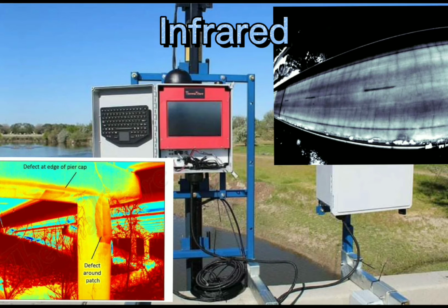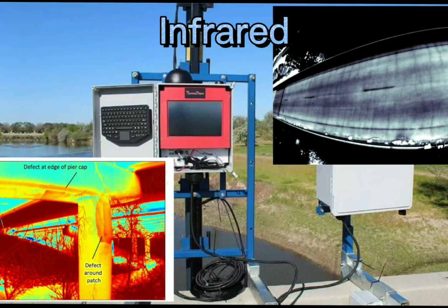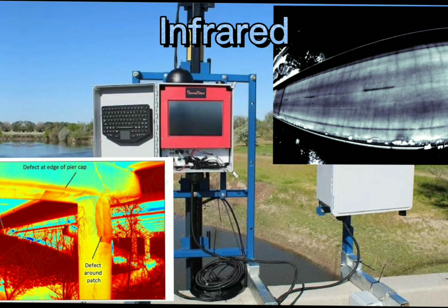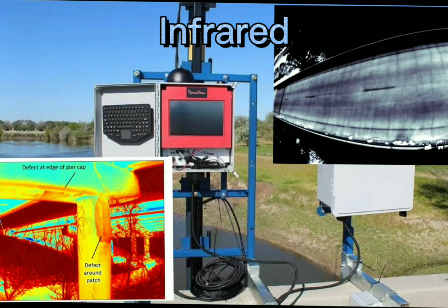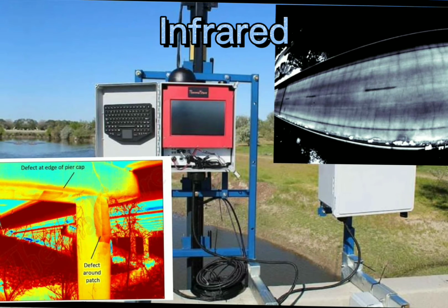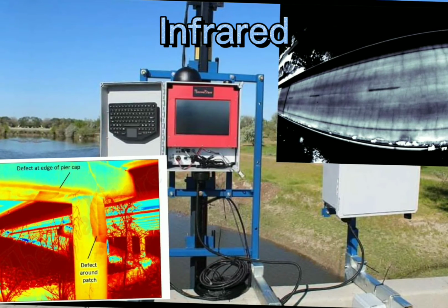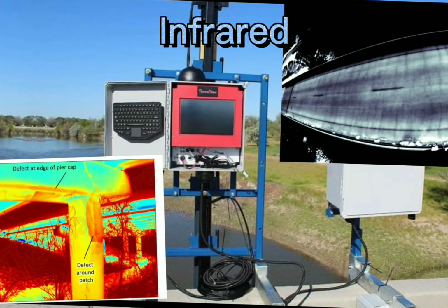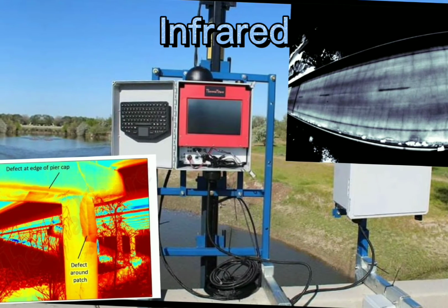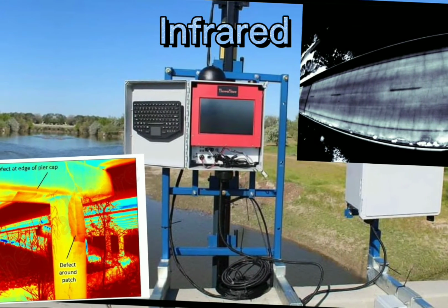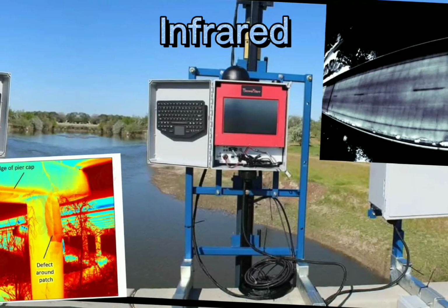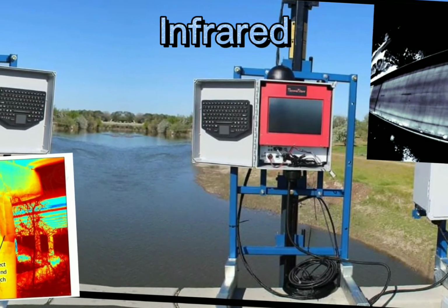Next are the advantages. It can be performed quickly and even in a moving vehicle. Last are the disadvantages. This method cannot be performed on bridges with asphalt overlays. The data must be obtained when there is a large thermal gradient between the bridge and ambient temperatures.